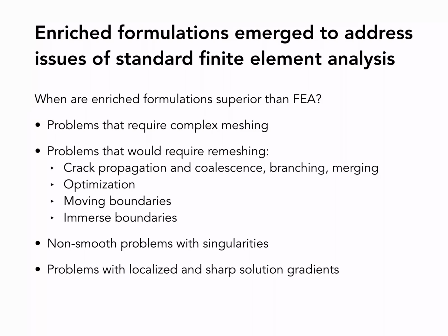Problems with localized or sharp solution gradients are also suitable. If we add to the formulation a function that has a sharp gradient, then we're basically asking Galerkin to try to use this function to reduce the error. If the function is useful, it's going to assign a generalized degree of freedom to that function. If not, it's going to assign what? Zero. So all these are problems where you can really take advantage of this enriched FEM.